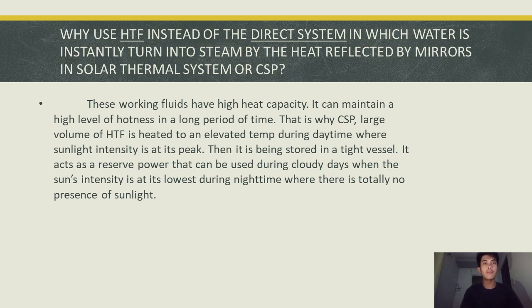Even when used within 15 to 20 degrees Fahrenheit of the recommended maximum temperature, the degradation rate of most heat transfer fluids is significantly higher than when the application requires a temperature within 30 to 50 degrees Fahrenheit of the fluid's maximum temperature.